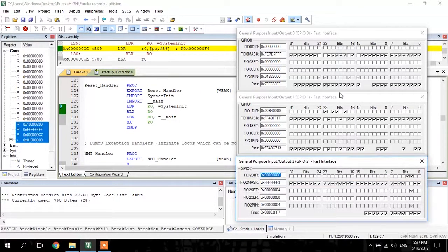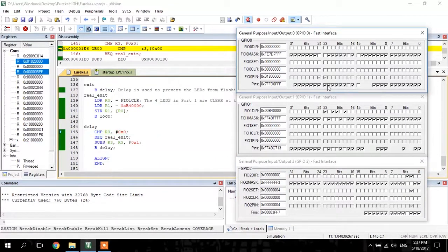So firstly, we set all the input to 0. Okay, at port 0, the pin 0.23 is set for up button. So when we tick the pin 0.23, which means that the up button is pressed, it comes out the output at P1.18. This can be explained when the person gets into the washroom, the PIR sensor will switch on the light automatically.